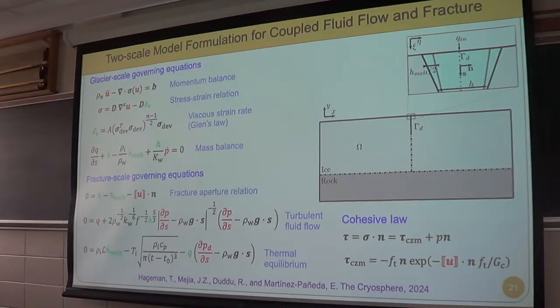And the governing equations are kind of scary, but I'll try to just give the big picture. So let's say you have the entire glacier, right? So this is 4 kilometers, let's say, wide, 1 kilometer thick, kind of representative of that location in Greenland that we were looking at. And the fracture is very thin, so it doesn't make sense to use phase field because it's so thin as a fracture. We use interface elements, which Pavana, you use a lot in your modeling. So we borrowed it from the composites literature and applied it to ice here.